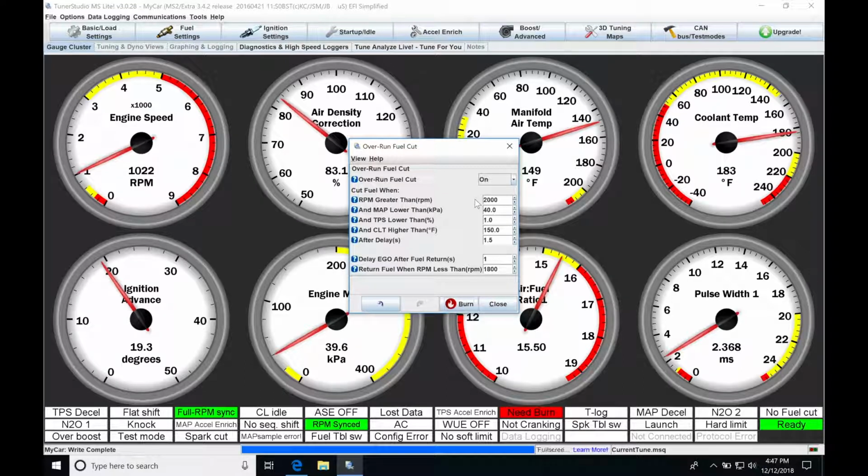If you have it too low, you're probably going to see stalling, or the engine's going to bog down as you're coming into idle. So we want to avoid that. We want to set it at least 1000 RPM higher, again, with a lightweight flywheel. With a normal weight flywheel, you might want to set this to at least 600 RPM. But that should be some good guidelines. These should be pretty much spot on to get started if you're using your decel cut.